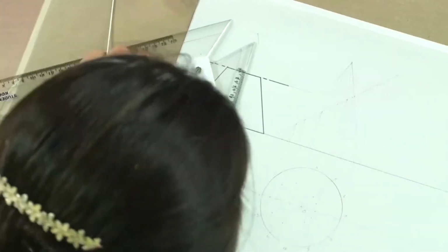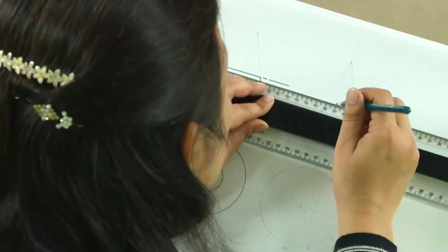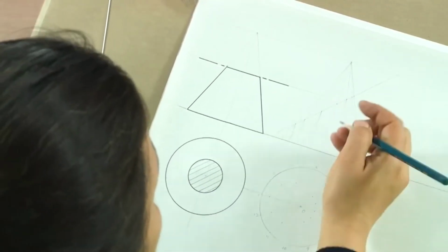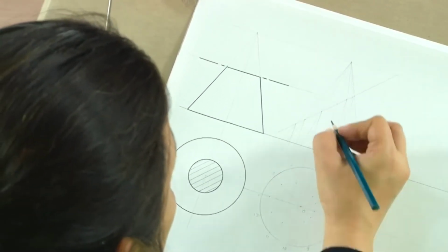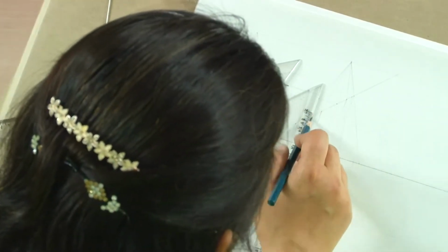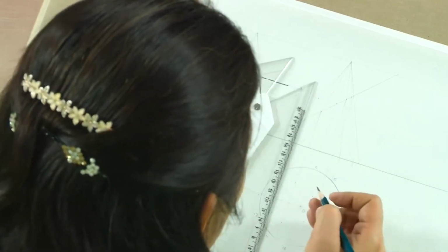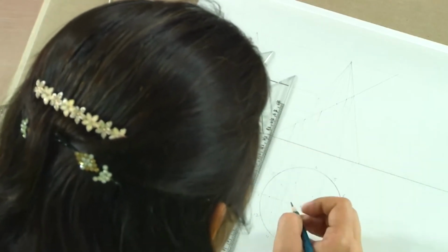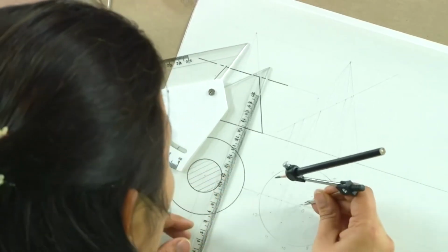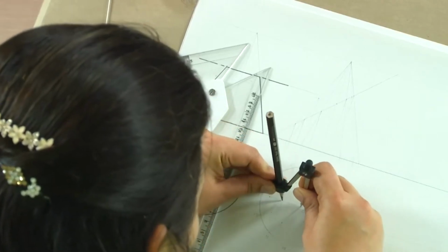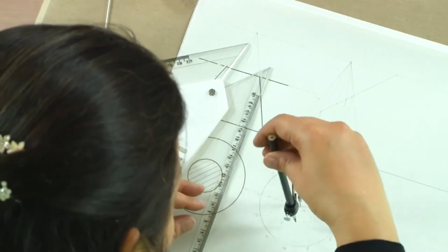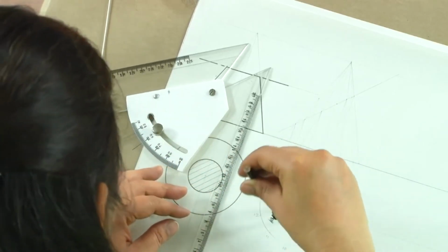Now, for this one, if you remember the same concept, if we were to have a section plane parallel, what we will get is a circle, at the same distance on these two generators. So, we will take the same distance at this generator here, so this is this point, and now the same distance as this point has from the apex will be the distance that we will have on these two generators.